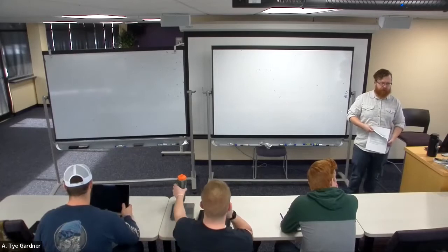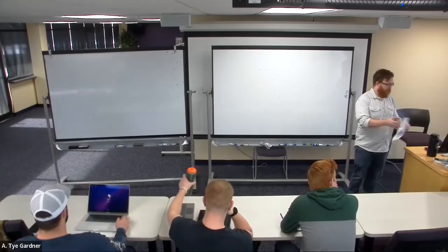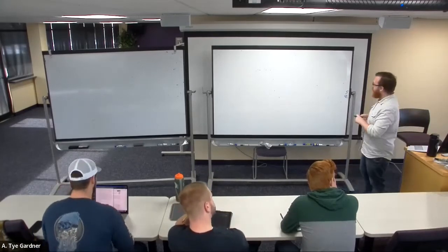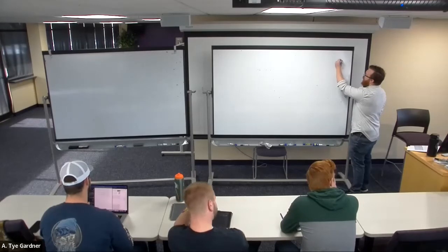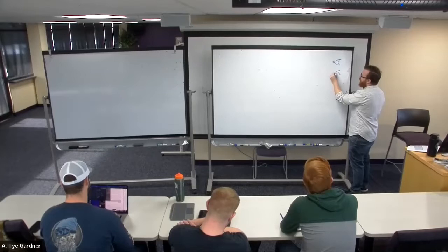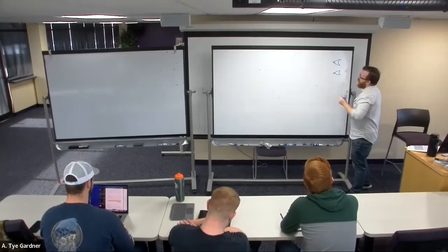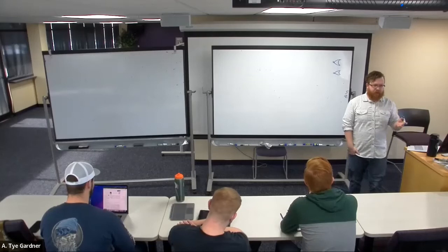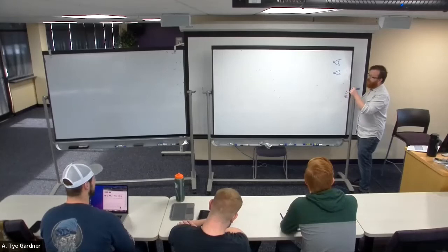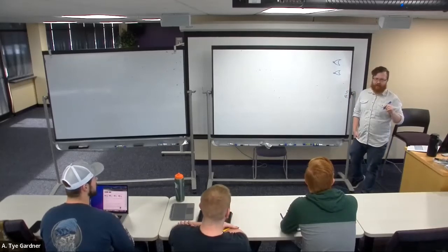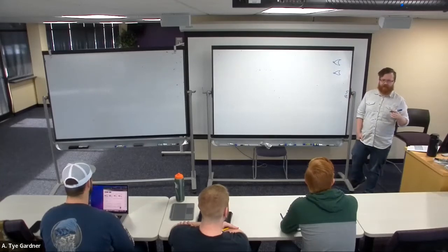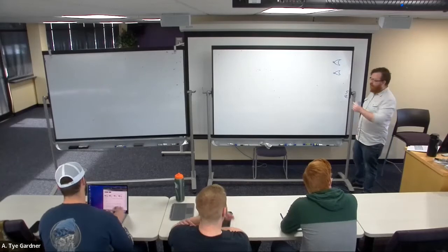Because we're going to use the same circuits that we've done before, but we're going to do it in a clever way. So the first thing that we're going to do is set up a couple of NOR gates. And if you know what Ouroboros is, which would be a great question on the exam to see if you're reading the instructions, because I'm sure most of you don't, right? It's the snake that swallows its own tail, goes on forever. We're just going to set up a situation where the information can chase its own tail, right? That will help us remember what's happening.